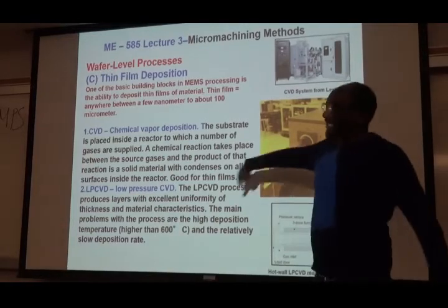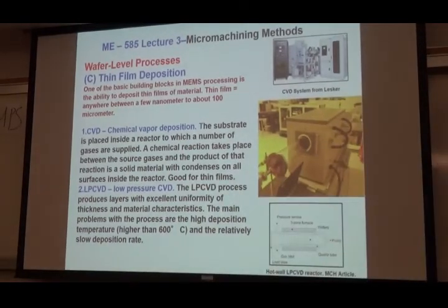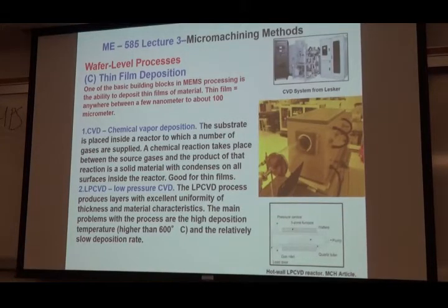So, it turns out we don't want to do the high temperature always, okay, the 1,000, 1,200 degrees Celsius, not for every material. So there are certain materials where actually you could do a low pressure. Again, with CVD, by the way, it's typically 1 atmosphere. We're not going to pressurize things, okay? Again, as a piece of knowledge, just like the way I told you about the temperature, right? Never more than 1,200 degrees Celsius or 1,500 degrees Celsius, okay?